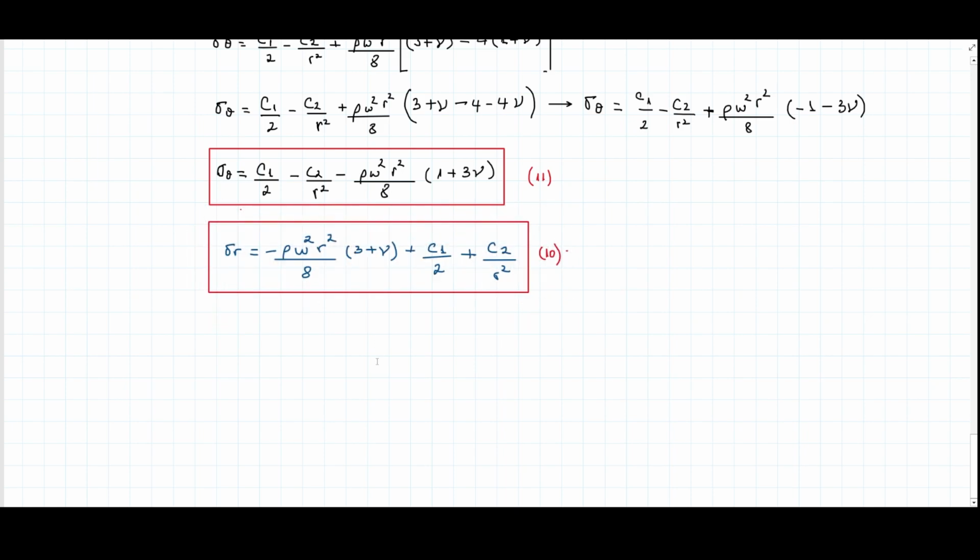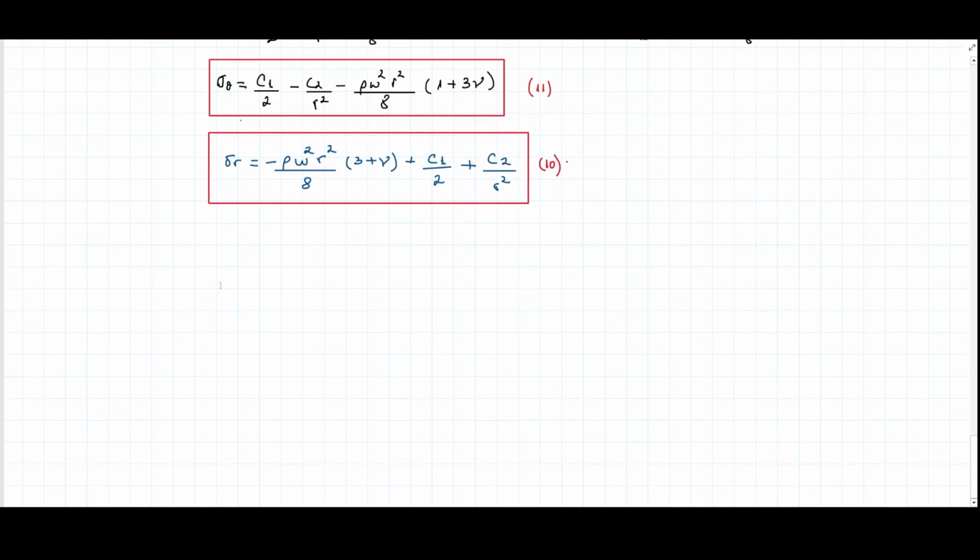Now, if somebody asks us how much the circumferential and radial stress are, well, we have the two equations. The only thing needed is to find out the values of the integration constants. And it means that we need to work with boundary conditions. Let me write a couple of boundary conditions; that's something you're going to do during the exercises, but it is important to write them down here. So, possible boundary conditions.